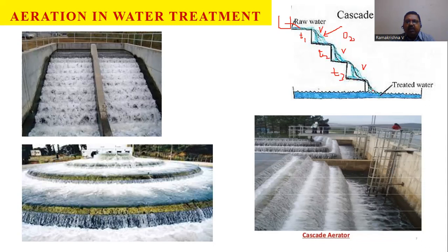Finally, when you reach a point where there are excess gases, either at higher concentration in the water, they will escape into the air. If something is less in the water, it will get added from the air. All such things will happen. Then your treated water is entering the next stage. There are a number of cascade tower configurations.